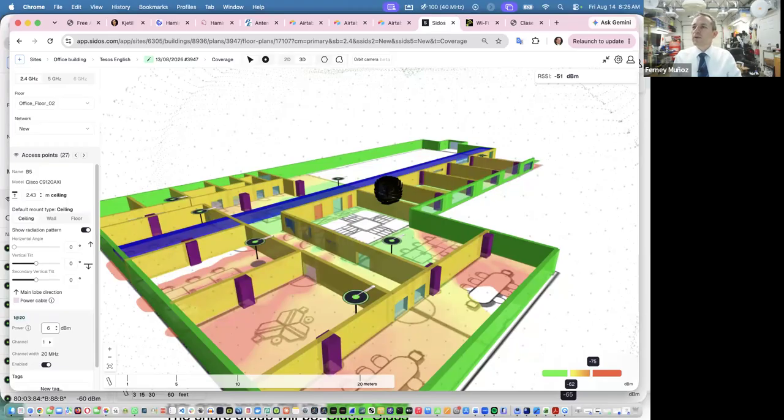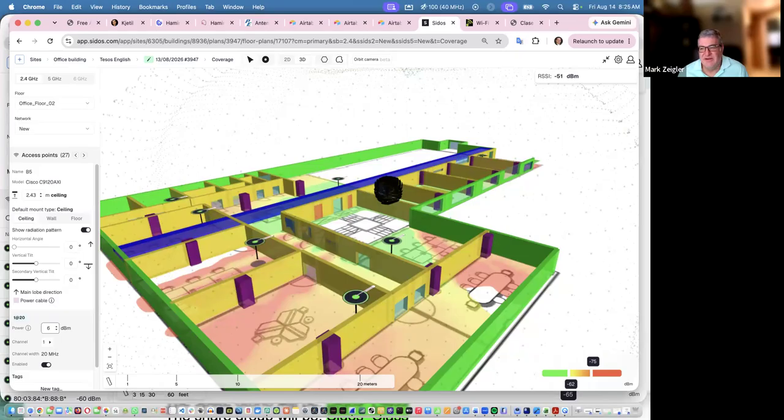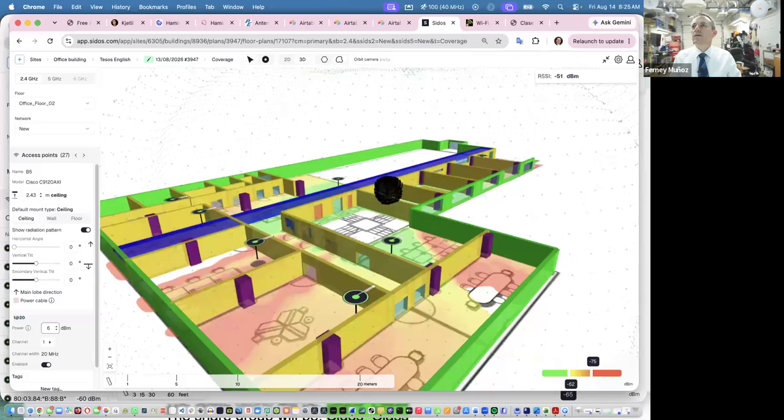And Mark, looks like you're playing with it big time, huh? You have the scale in a weird... What's the measurement? What's the dimension? I can't remember the number to get it set. 14 meters from here to there. Very good, thanks. But then notice that you don't have to scale every floor. Once you scale one, the floor alignment points, they better be at the same distance from each other, so it automatically does the scale, which is clever, okay?